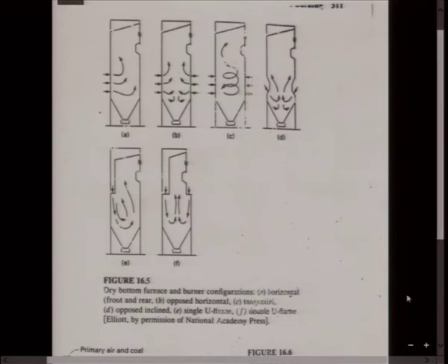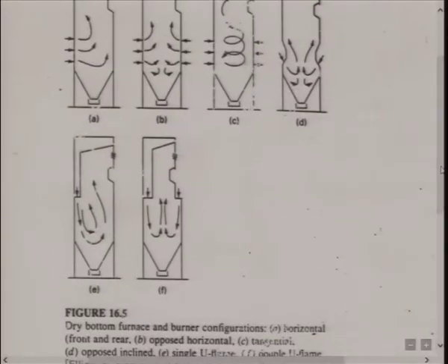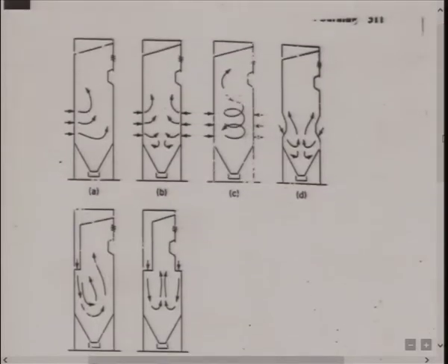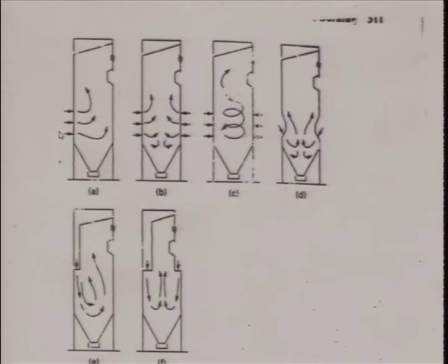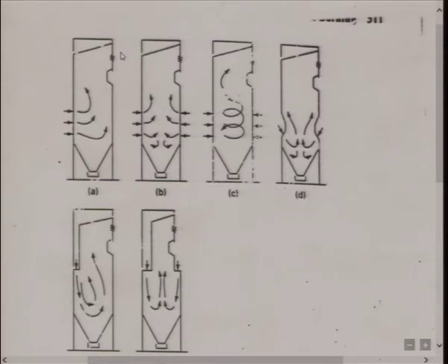This is better probably. So these are different furnaces which are used in power plants. If you have studied power plants and thermal power generation by solid fuel combustion, coal combustion, you probably are familiar with the shape. So this is the boiler, right? You have coal and air coming in through injectors, injected into the combustion space, and then burning takes place, and the hot gases move typically into the second pass of the boiler.